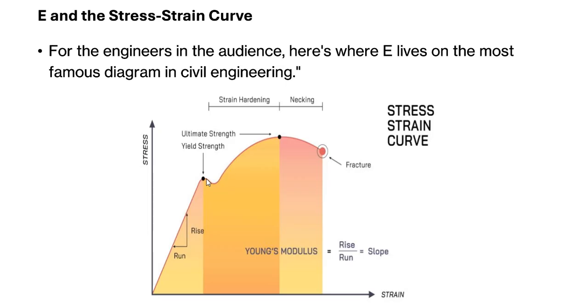See, by increasing the stress, the strain started increasing, but it is not regaining. It has curvature, which means it is not getting back into the normal position. So it is a non-elastic zone. It is getting into the plastic zone. That's why it is called yielding.